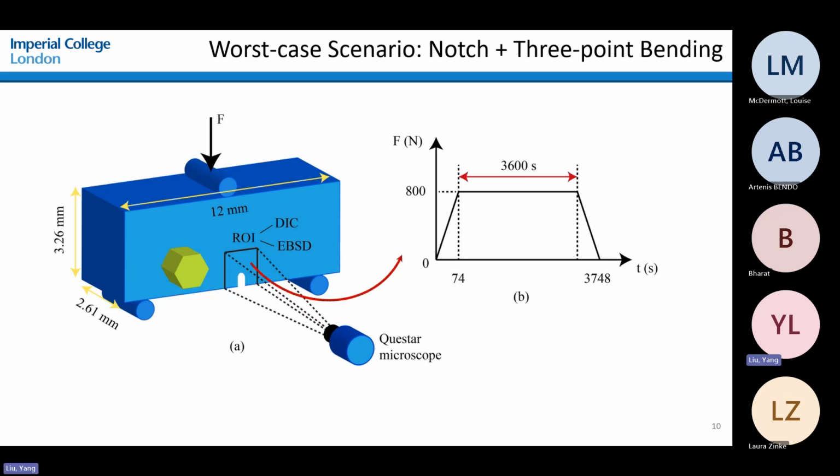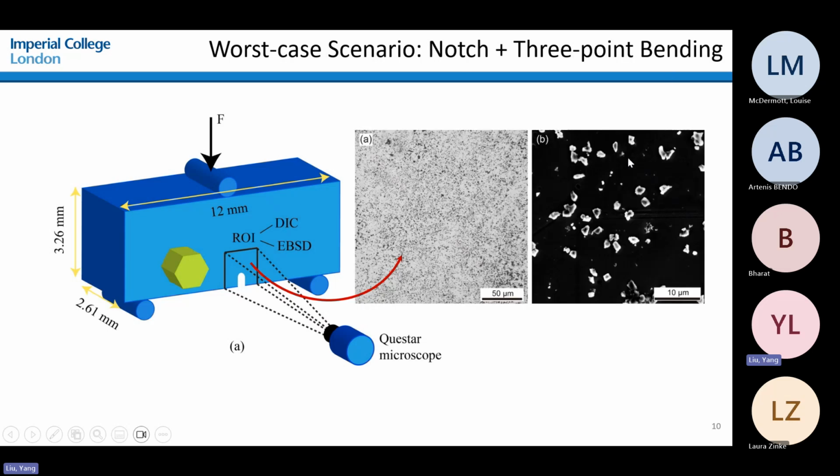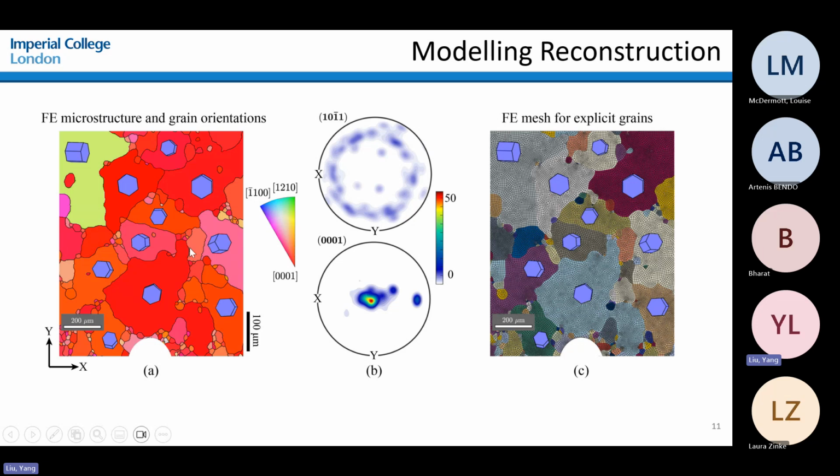And on the surface of the sample, we put on speckles, where the speckles are about 1 to 2 microns, so we can understand this behavior at this length scale. And you can see that these grains we created specifically to enlarge them so that we can understand the crystal level behavior in a much more detailed fashion.